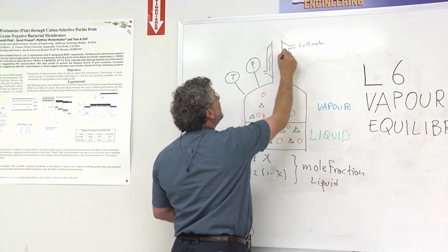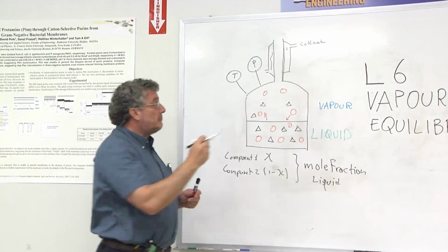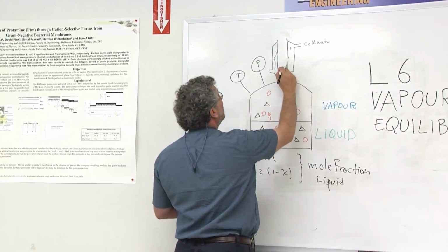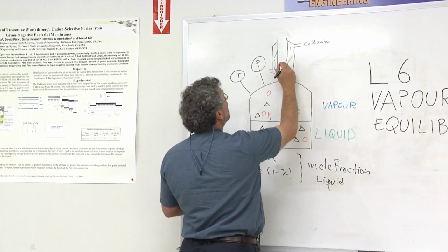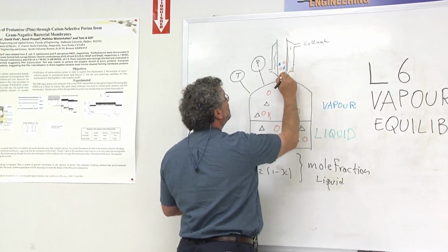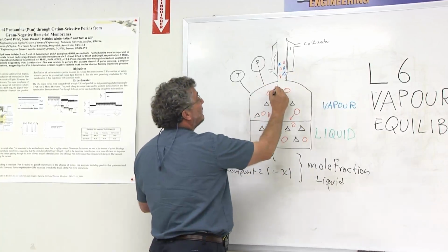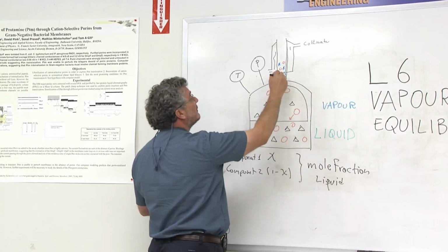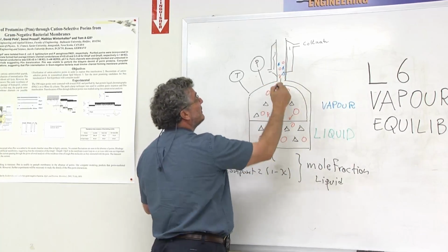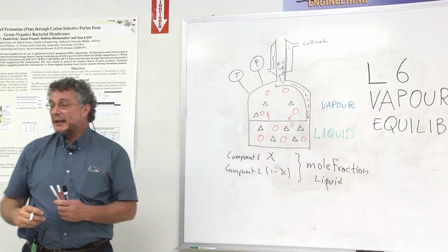It's going to be circulating, and it's going to create a trap so that our molecules that are in a vapor state and are trying to escape get condensed, and we give them an alternate path to return to the liquid. So when they condense, they don't drip there directly, they go through another path and go back.